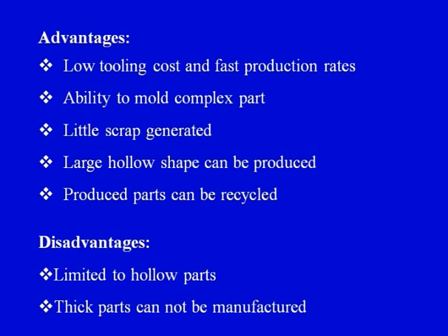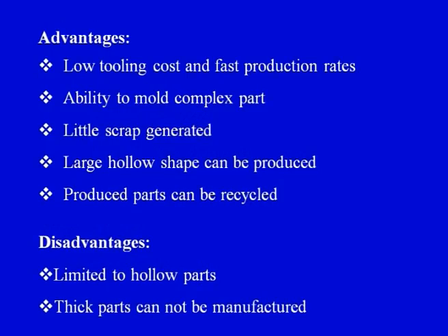But there are a few limitations also. And what are the limitations? The limitations are that the process is only limited to hollow parts. Why? Because we have a hollow plastic raw material which we are inflating by the air pressure. So this particular process is suitable for hollow parts only and cannot be used for solid parts. Thick parts cannot be manufactured. So the wall thickness in case of blow molding is limited, so we cannot make very thick products using the blow molding process.